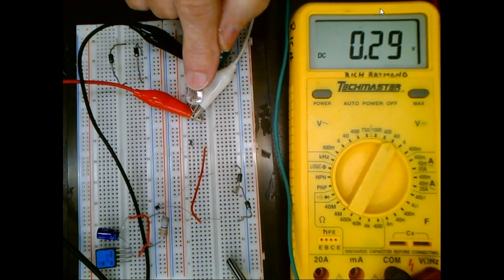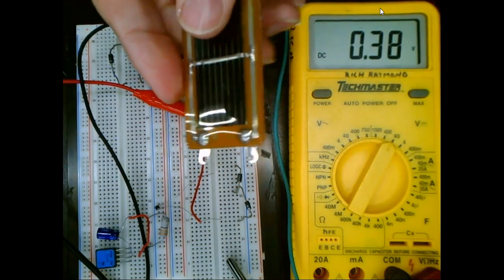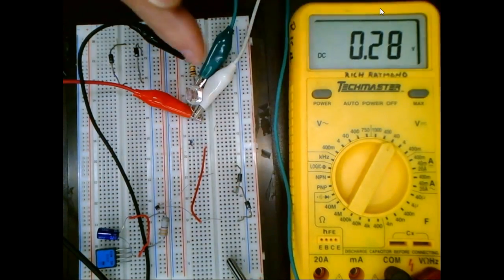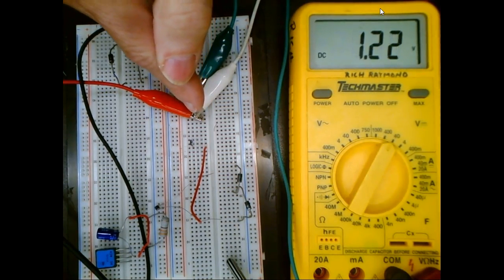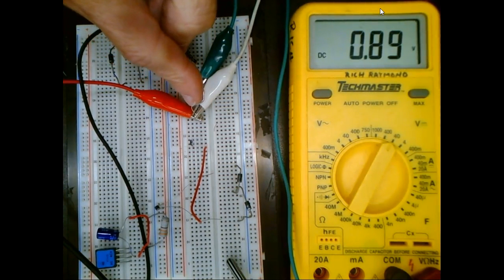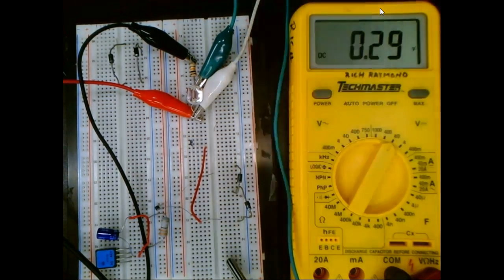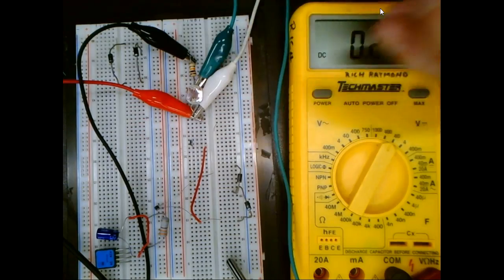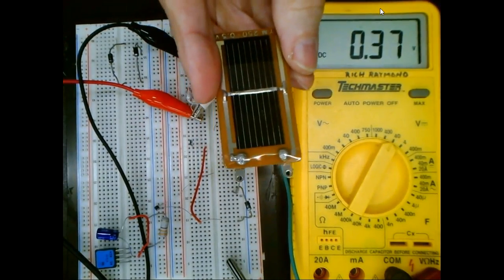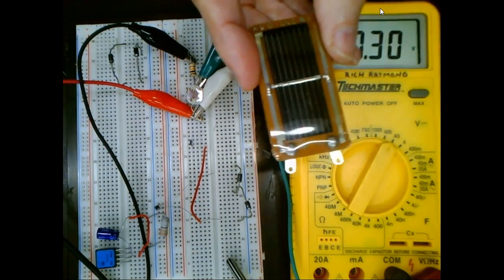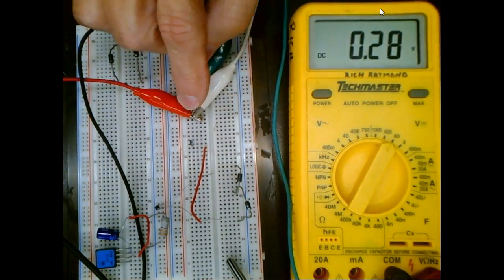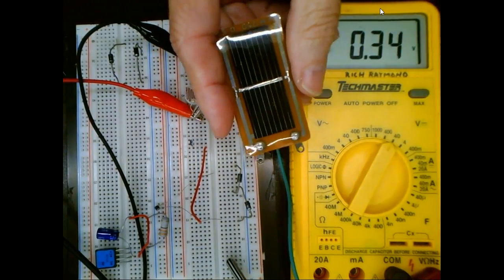Well, this has to be powered. This don't. This generates power. This guy has to be powered, right? So what we would have to do on this, if my sensor is out there, I would have to have the Wheatstone bridge and everything out there, right? I would have to run power out to the sensor, right? You understand that? So that means I'm gonna have at least 4 wires going out to my sensor. This guy right here, I'd have how many? 2. Because this guy doesn't have to be what? Powered. This guy would have to have a power supply. This guy generates his own power.